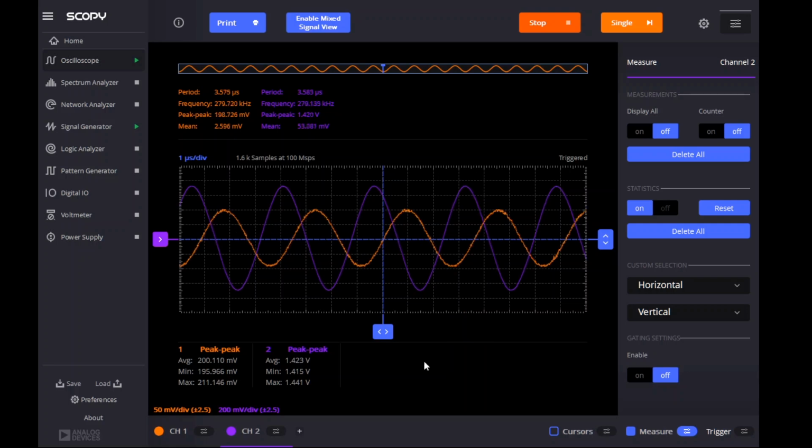We'll take a look at a table of results in more detail, but that's the basic approach. You start by verifying that the system's working with a low frequency waveform. Note that the gain is what you expect it to be. It should be near the theoretical gain. And then you can use the network analyzer to find the frequency at which the output amplitude is 3 dB down, and that frequency becomes your bandwidth. Multiply that by the gain to get the gain bandwidth product.